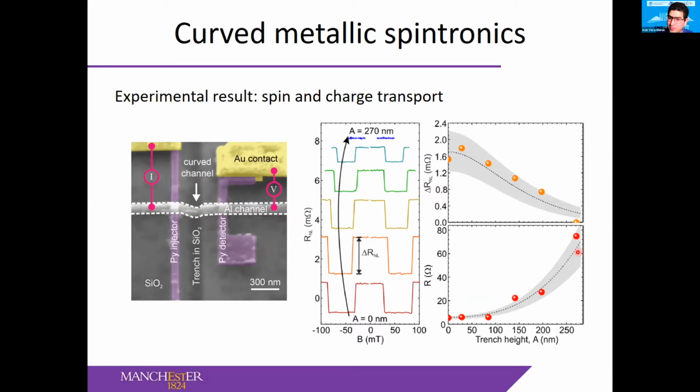And this opposite response, at least to first order, we can understand as the result of the resistance of the channel increasing because of the longer length and thinner regions. But then at the moment of trying to understand the actual trend and model it, which is what these lines show, we actually failed initially because there was no proper model to apply to such inhomogeneous channels.